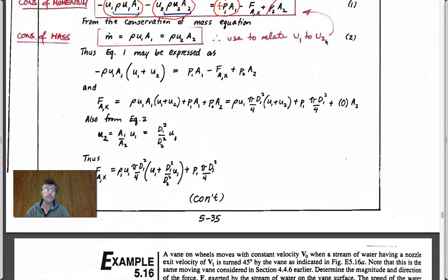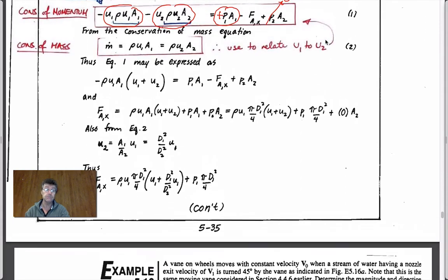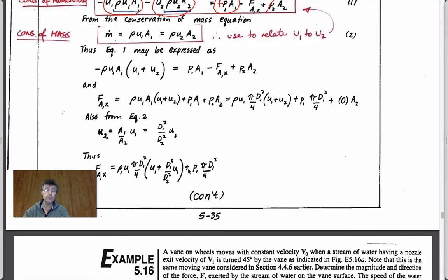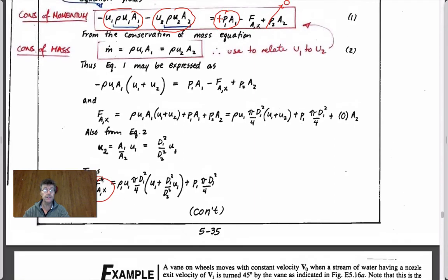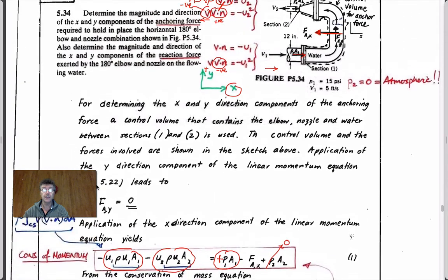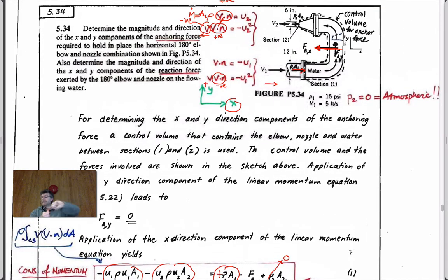Not calculated, but, or it isn't. No. It has to be positive, right? Because all of these other terms are positive. So the force is positive, and so the force you have to hold this in place with, as it's flowing water out of this monitor, is to physically hold it with a positive F magnitude, which means it's a force in the negative x direction. Just by the way you define it.